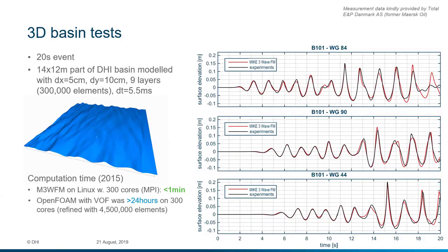Here it took less than 1 minute to compute. We had a time step of 5.5 milliseconds, a discretization of 5 centimeters in one of the horizontal directions, 10 centimeters in the other direction, and a vertical discretization of 9 layers.